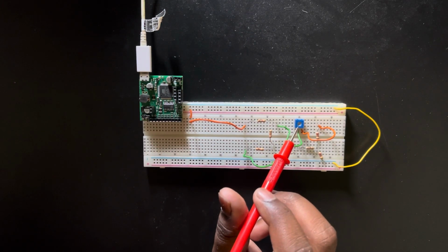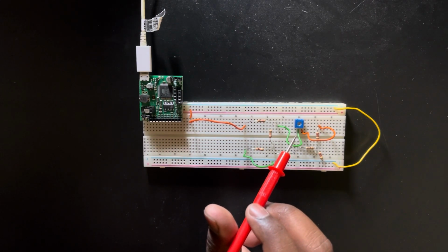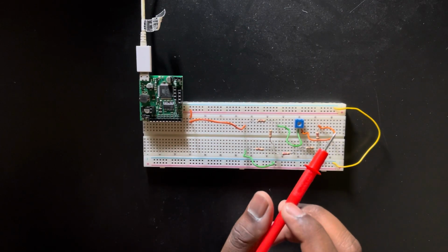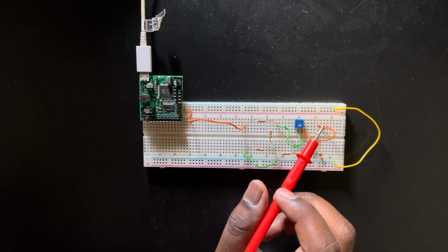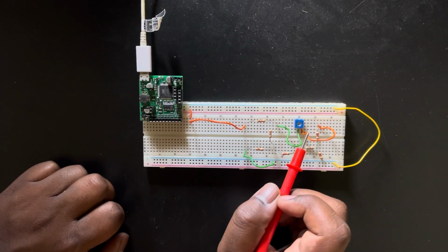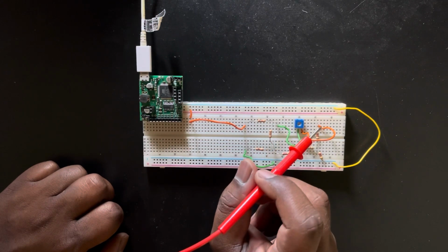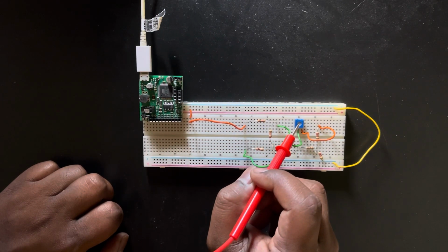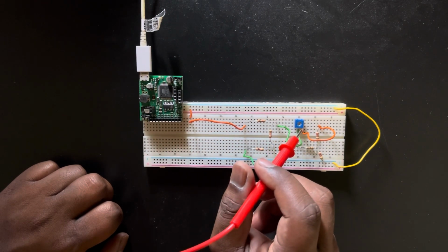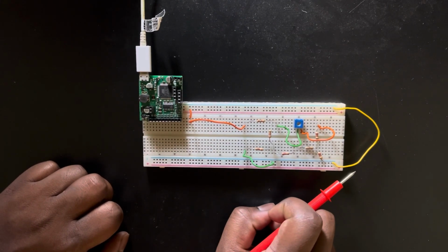The potentiometer is for this: if you observe node 5 and node 3, the resistor between those two nodes is 1.2 kilo ohms, right? I don't have that, I have 1 kilo ohms and 1.5 kilo ohms. So what I tried to do is set the potentiometer in a way that its resistance value is 1.2 kilo ohms. Now it's connected to the circuit, but before, it was totally detached from the circuit, and then I adjusted the resistance, and when it was around 1.2 kilo ohms, I set it into the circuit.